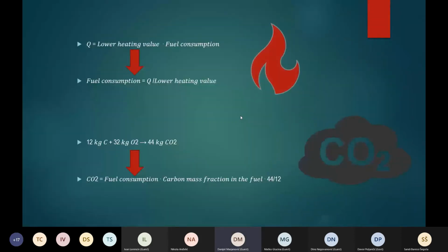The fuel consumption was given for all the different loads, and the lower heating value of fuels is known. That gave way for the calculation of the heat generated from the steam generator, which then enabled the calculation of the fuel consumption of different fuels needed to have the same amount of heat generated. That data is then used for the calculation of carbon dioxide emissions for 18 different fuel types, as before mentioned, for comparison and for all the loads of the generator.